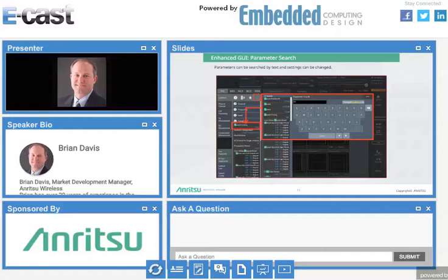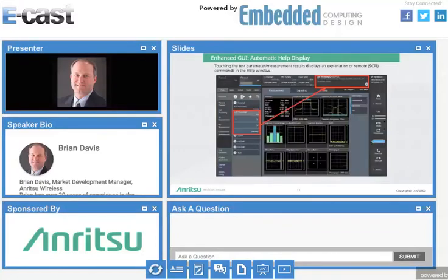Here's an example in more detail of the parameter searches, so you can get the keyboard pop up. It'll give you a green color there to show all the parameters that start with CH. There's an automatic help, so if there's any parameter that you want more detail on, what does this do, what does this change, you'll get a little frame on the top right where it'll explain what the parameter is, and then if you expand down on that, it'll give you SCPI command information.